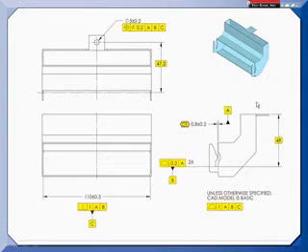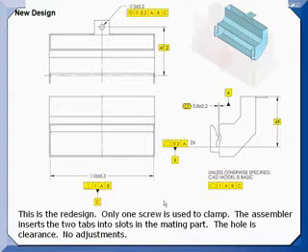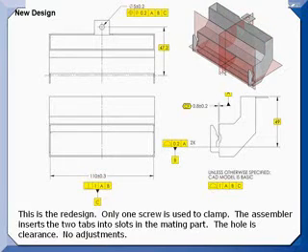So now we've created alignment features. Datum feature A is this irregular feature of size here between this little bump, and actually there's 2 of them, one here and one here, and the surface. B is these 2 surfaces down here, which are that spot and that spot right there. And then C is this width that I was talking about. So now I have a nice datum reference framework, and we can kind of see the datum planes here for our dimensional origin. So we had to create those alignment features because they weren't all that obvious.